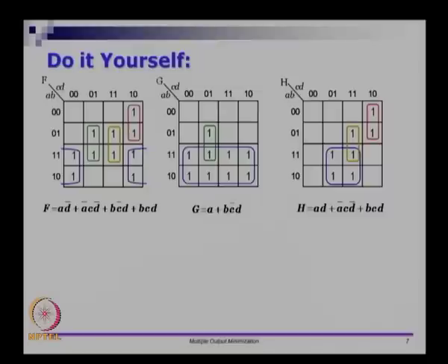If you want to look at the smallest number of gates that is needed to implement this 4 input 3 output circuit, it may not be possible at all. We may not be able to get the optimal one for every single combination of 3 outputs and so on. So instead what we start looking at is synthesis of circuits. Synthesis means we want to create a gate level description of these truth tables. However, we may or may not have the smallest number of gates. Getting the smallest number of gates is not always possible.